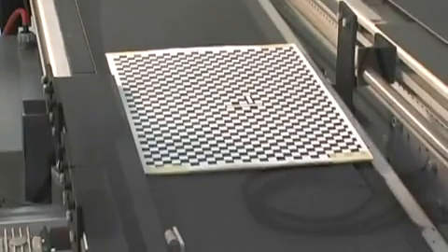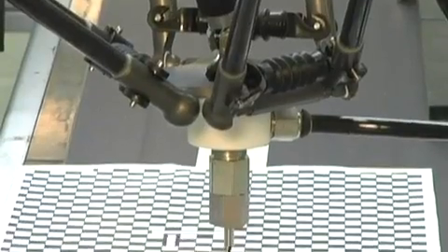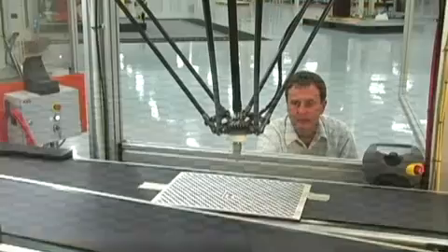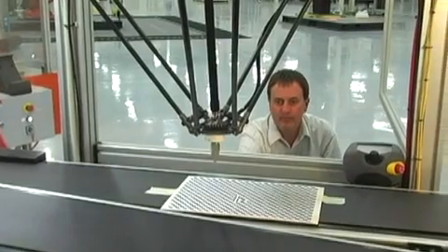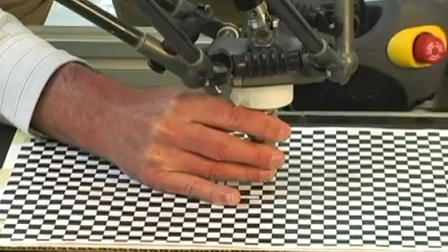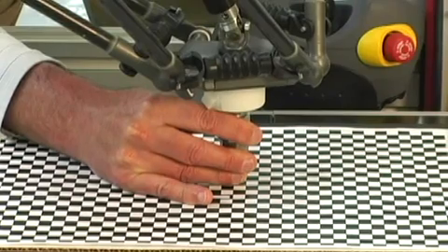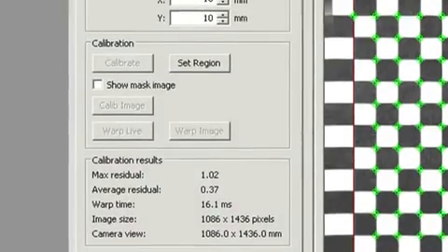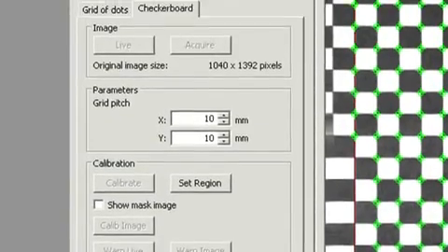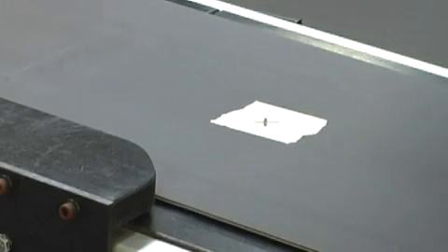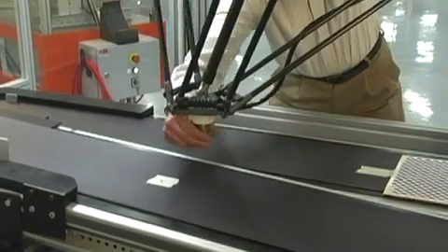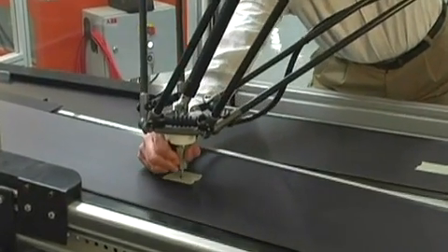on the conveyor. Now that the camera is calibrated, the calibration grid is then moved to the robot so that this information can be taught to the robot. And with that, the robot now knows where the camera origin is located, as well as the X, Y, and Z coordinates of conveyor 1. After a similar operation is performed on conveyor 2, the setup of the line is now complete, and we can begin the creation of the project.